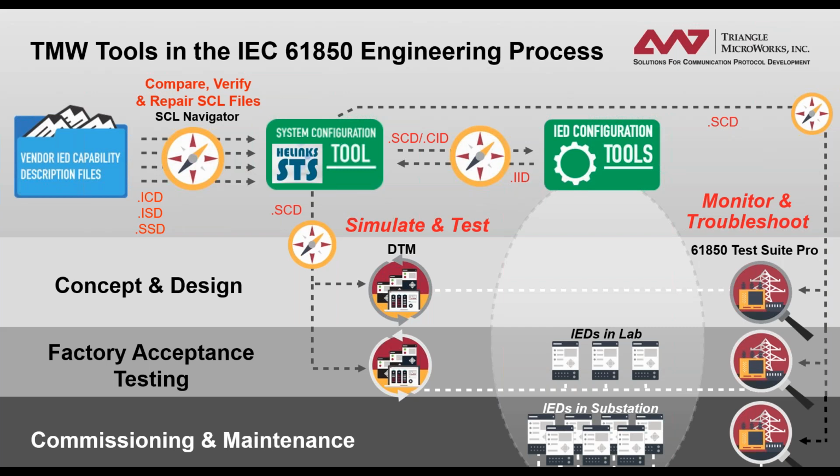I would say yes, with some caveats, Christoph. Yes, there is part 6 of 61850 that defines the system configuration language, has an annex that defines some constraints and how mixed systems shall be working. As one condition, it is required that the system tool shall be of the highest edition. So if I have edition 1, edition 2, and edition 2.1 devices, it is assumed that the system tool supports edition 2.1. And then we have, in some cases, what we call downgrading.